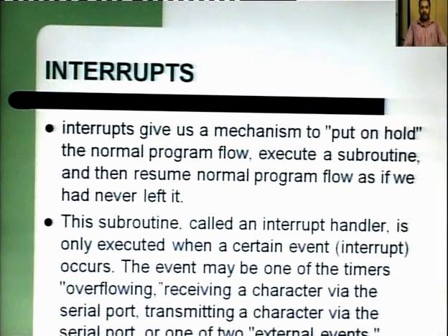As you have seen in the architecture, there was a block named interrupt. An interrupt gives us a mechanism to put on hold the normal program flow. By holding the normal program flow, it executes a subroutine. The microcontroller executes the subroutine, and then it resumes normal program flow automatically, as if we had never left it. The microcontroller automatically saves the program counter contents, so that it resumes from the same location.